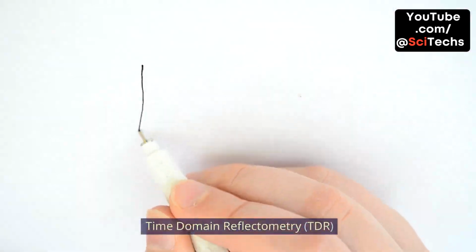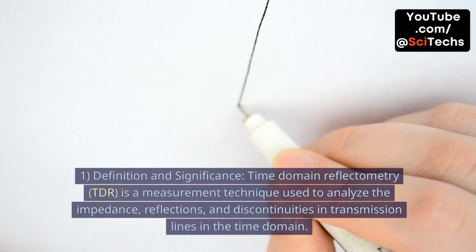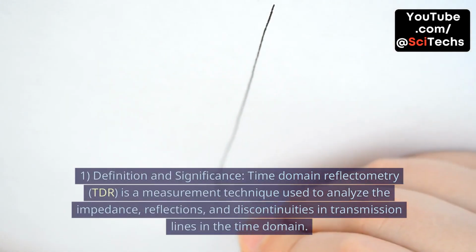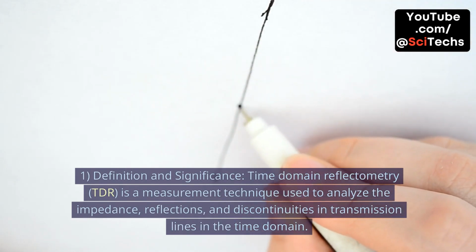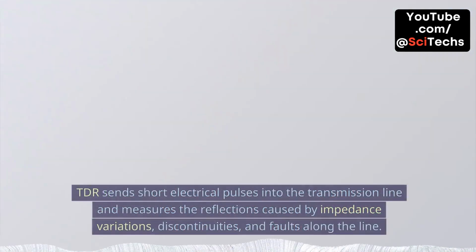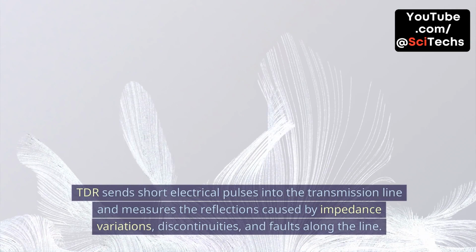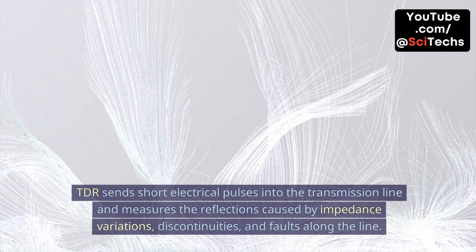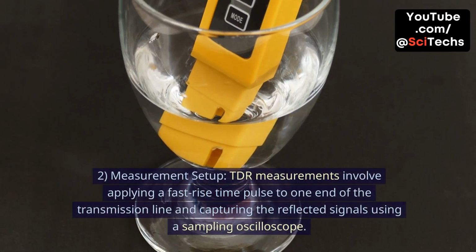Time domain reflectometry, TDR. 1. Definition and significance. Time domain reflectometry, TDR, is a measurement technique used to analyze the impedance, reflections, and discontinuities in transmission lines in the time domain. TDR sends short electrical pulses into the transmission line and measures the reflections caused by impedance variations, discontinuities, and faults along the line.